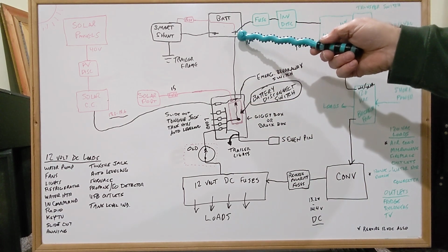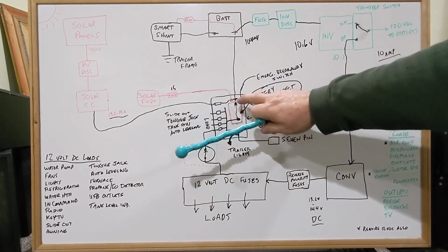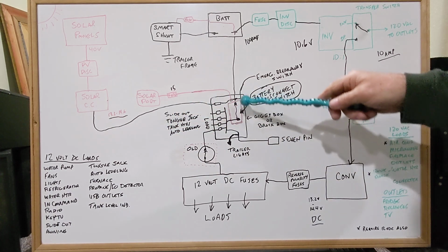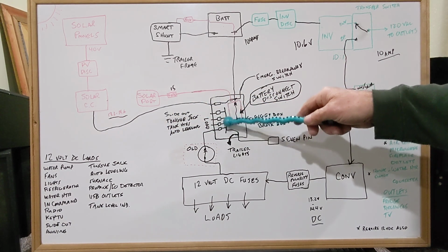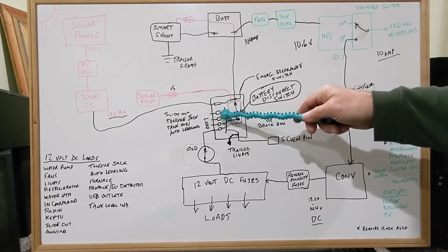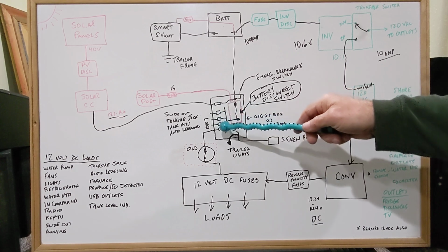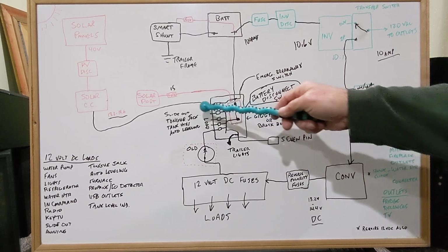So on the Brock box or the Giggy box, the battery's coming in, and right here is your battery disconnect. With the battery disconnect on, power's coming down through here, and it connects up to here. If you pull the cover off the boxes, you'll see these little silver boxes, auto-resetting circuit breakers, and they're feeding some of your bigger loads.